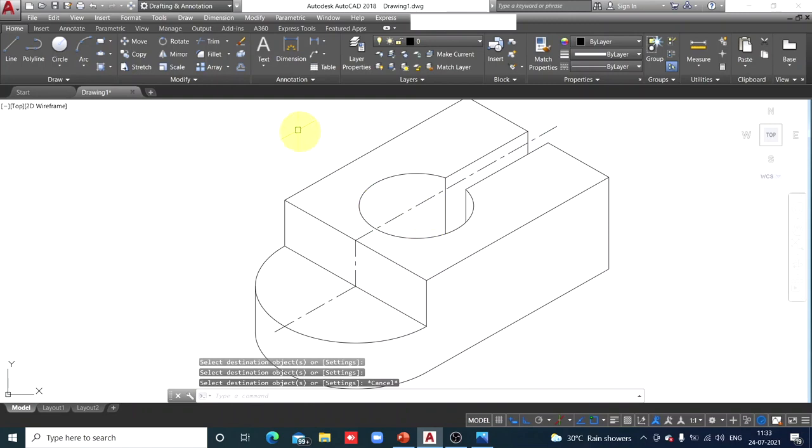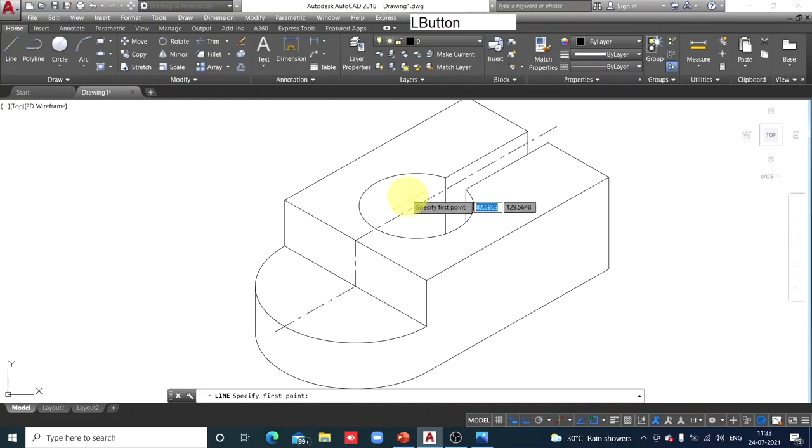Similarly, the center line parallel to width axis, length and width in the top surface. On the top surface, this opening is. So let's draw the line. When you move your cursor after selecting a command, I have selected the line command, when you move your cursor on the circle, the AutoCAD software will indicate the center of this circle. Check here. Here it is. That circle suggests you have selected center, but don't click here. Track that center and slightly outside the circle, click it, and through the center.